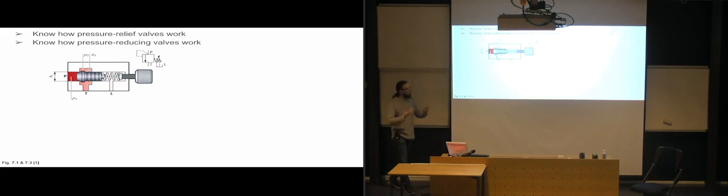So if you suddenly get a pressure peak in your system, whether it is a cylinder that's connected to something else and that other part suddenly jerks on the piston rod and creates extra force moving in, so basically just trying to compress the hydraulic fluid, or if it's a spike in the electric current to the motor, and the electric motor suddenly increases its rotational speed a little bit, which will again increase the pump rotational speed a little bit so that it outputs a higher pressure.